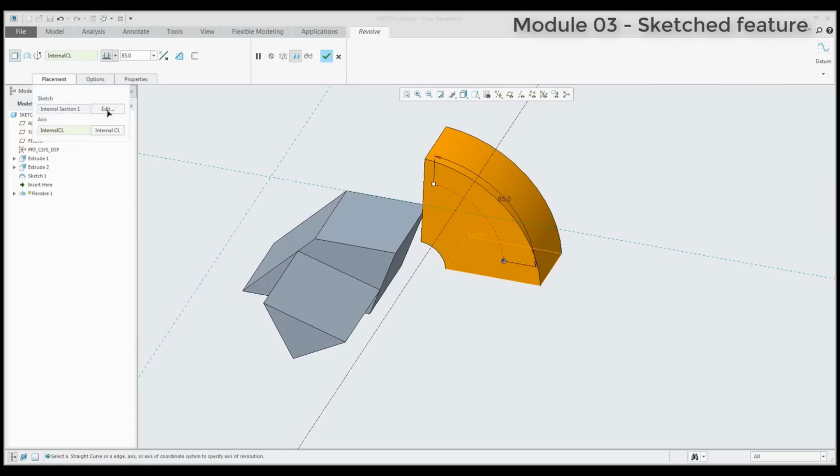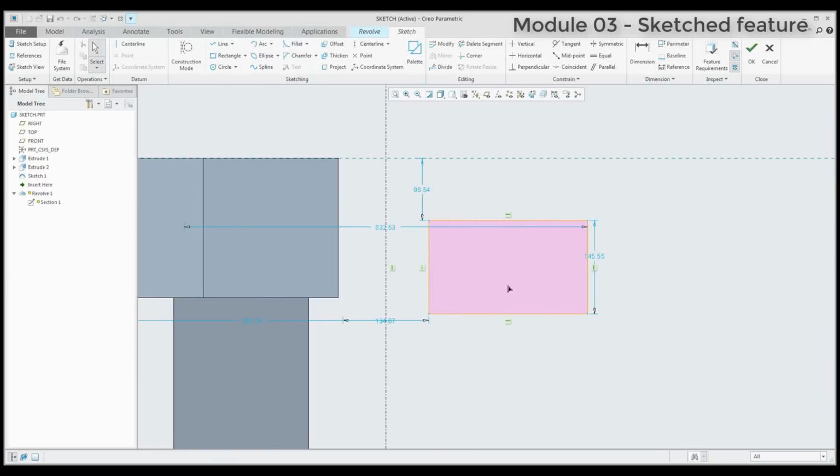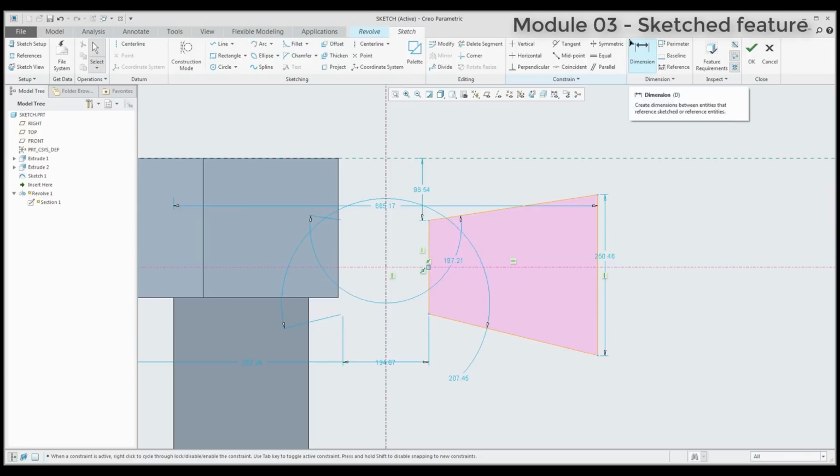If I go back to the sketch and you would like to create, for example, a symmetric sketch here, yes, you can use this center line or right mouse button and create the center line. And you can place it directly here. You can destroy these constraints, and then you can change it a little bit, and what is necessary to do, set the symmetrical objects.